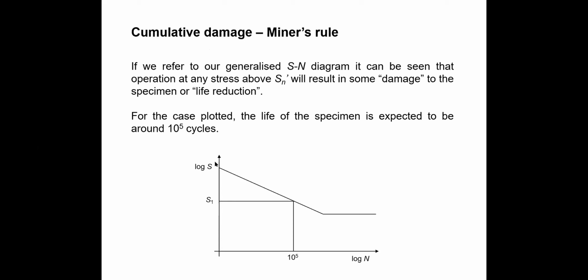So we will apply different types of ranges. We need to calculate the relevant stress range, how much damage it does to the specimen, and we will get the summation of all the damage and calculate the final strength. So that's how we can do the equation with this theory.